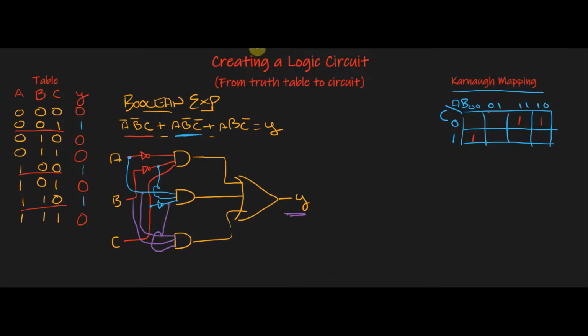So what I do is I group them together. Anything that's touching, for instance, these two, if there were 2 here, if there were 2 vertical, I could do those. If there were 4 here together, I could combine those. Here we only get these 2. Now what I do is I combine these. There's nothing to combine with this one, so I'm just simply going to write that one down, which was the A naught, B naught, C.